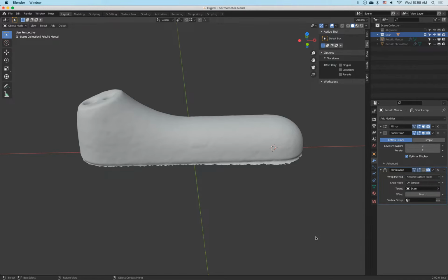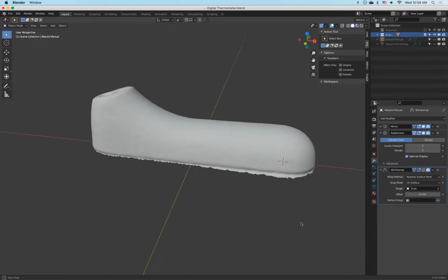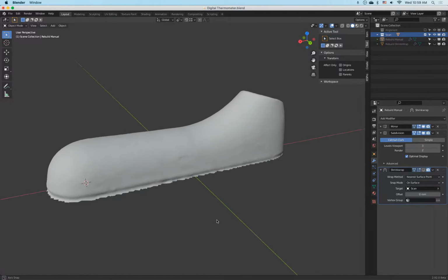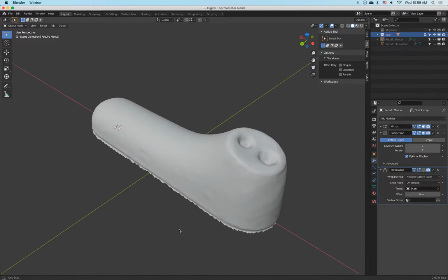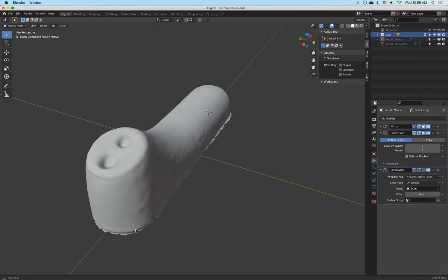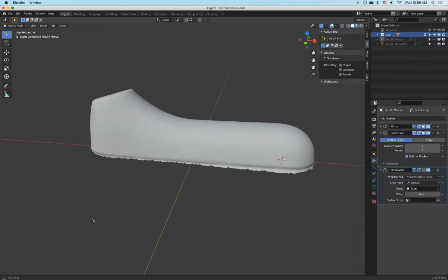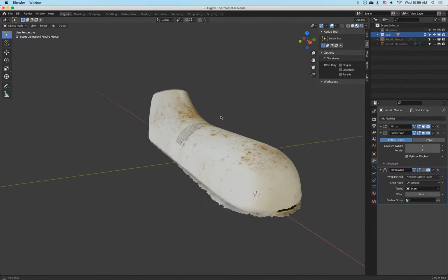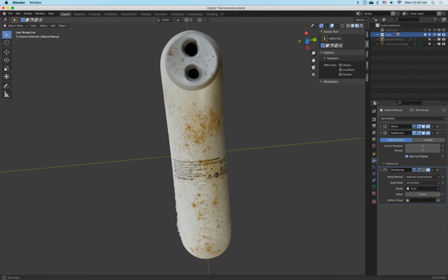In this lecture, I will introduce you to how to use 3D photogrammetry. What is 3D photogrammetry? Essentially, it's very simple. We take a sequence of photos walking around an existing object, trying to photograph every detail we would like to be turned into a 3D mesh. And then the images we will use with a software to then create, you guessed it, a textured 3D model.